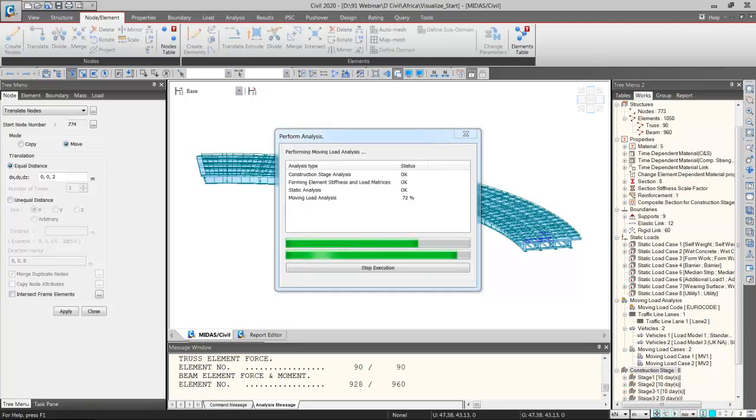All right. Yeah, some of you are also using the AASHTO standard. Well, apologies, I just saw your statement, so I did not consider AASHTO. But yes, we can perform the analysis with vehicles as per AASHTO. We can have the definition of load combinations as per AASHTO. Basically, load combinations can be automatically generated as per AASHTO, and you can also get the PSC design as per the American standard.